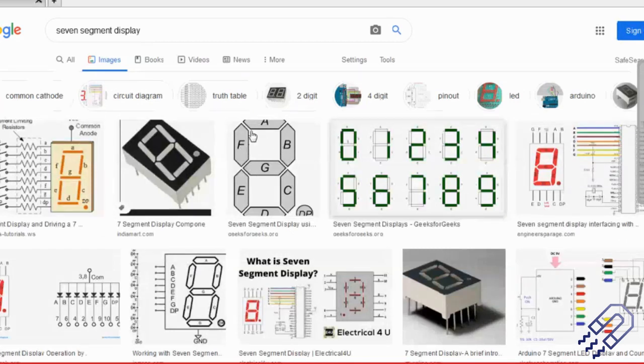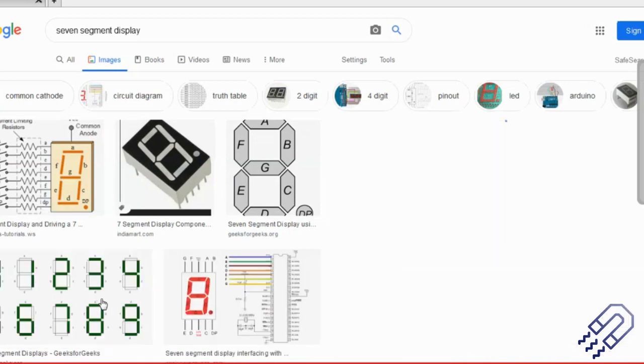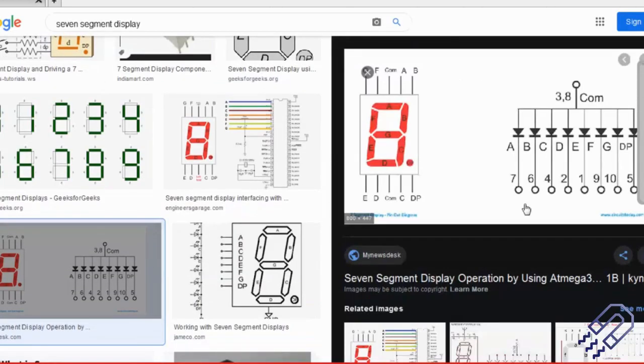You see A, B, C, D, E, F, G: there are 7 segments. This is on, this is on, this is on, and you get 3, which means F and D should be off. This is exactly how an LED display works. This is the basic circuit. I think this one is better, so you can look into this.